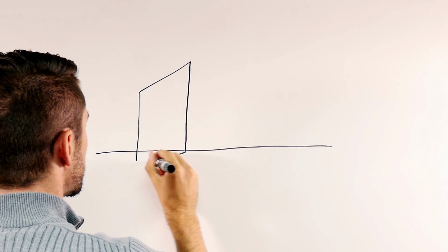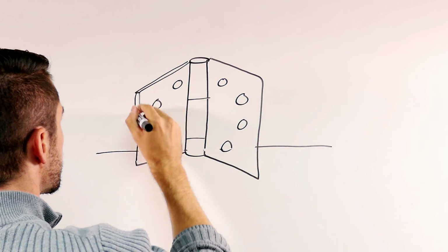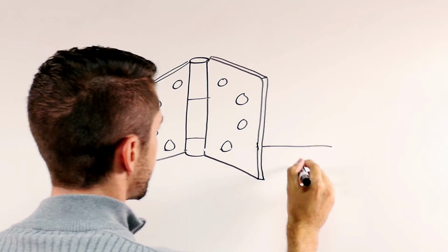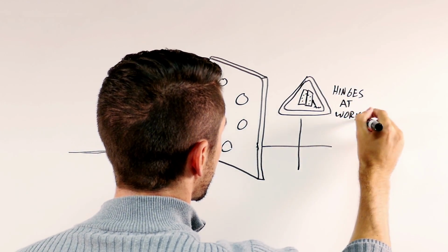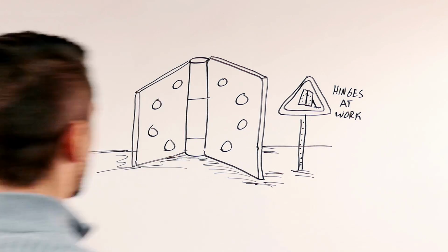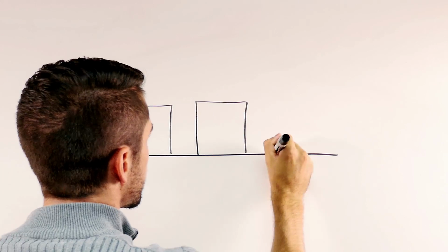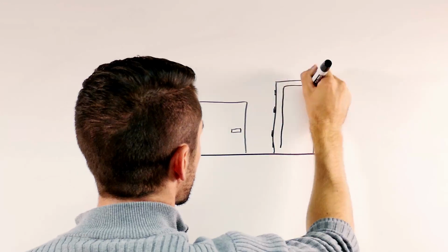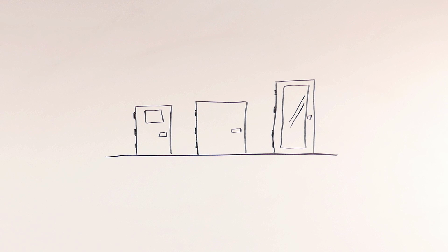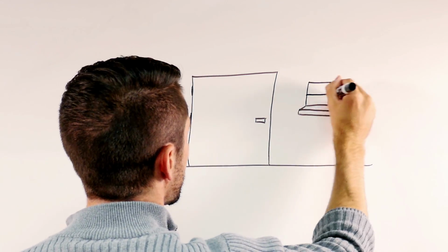In the world of commercial door hardware, the hardware one uses to hang a door is among the hardest working hardware there is. Today, doors are typically hung using conventional hinges, continuous hinges, or pivots, with the conventional hinges the most popular way. To the surprise of many new to door hardware, there is a lot to learn about hinges, in part because there are hinges that can accommodate almost every door, frame, and opening condition. This introduction will help familiarize you with some of the basic characteristics of hinges.